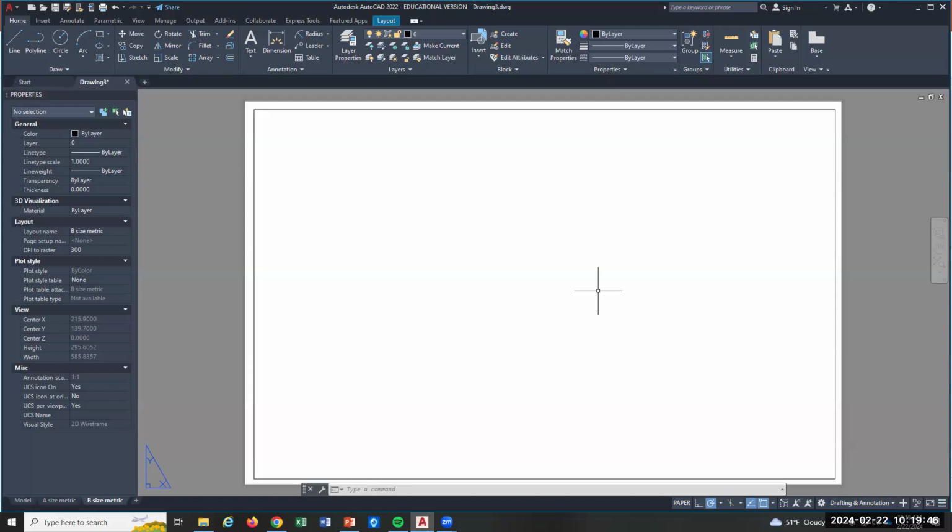Questions? It's not too difficult. You just have to remember to save it as a template file, right? And then use it when you start a drawing, but don't open your template file and then do a drawing. Anyway, you can muck your template up if you do that. And then over time, if you're setting up settings of AutoCAD, you can go back to your template and update that anytime, right? With new title blocks or another size piece of paper or whatever you want. But we shouldn't have to be recreating the title blocks and everything over and over.